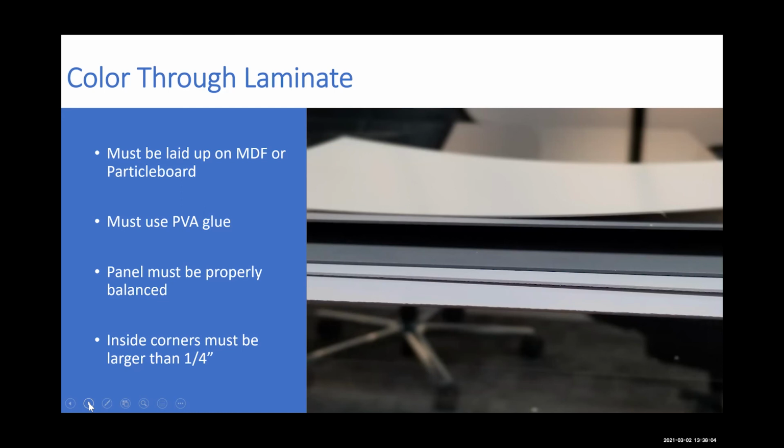It doesn't show that line, but you have to consider that it is comprised of all decorative paper and there's very little phenolic resin in it. So what does that mean? It makes it much more brittle. It's much more expensive, and it's very rigid and difficult to fabricate. And it's more susceptible to dimensional change, which means that they have to get the PSIs right when they're putting it on. They have to make sure they have adequate glue coverage.